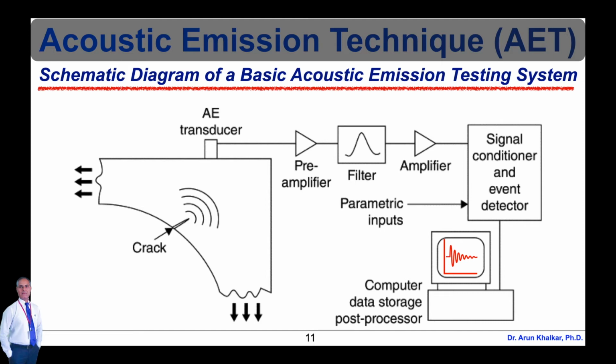First, the preamplifier boosts the voltage to provide gain and cable drive capability. To minimize interference, a preamplifier is placed close to the transducer. In fact, many transducers today are equipped with integrated preamplifiers.